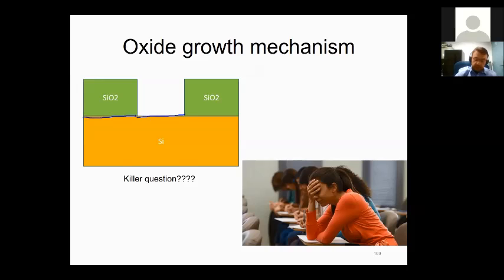That's one thing to remember. So let's look at this part here. If we start with this silicon level, it will get lowered down. 45% will be here. I will grow 55 at the top. Okay, that's good for that portion. How about the others? Now, the second important thing that we need to remember is the oxidants, let's say oxygen in this case, will have to diffuse through all the oxide here. So that makes this process on the sidewalls to be slower than the process here, because here it just sees the bare silicon and it can grow the oxide much quicker.